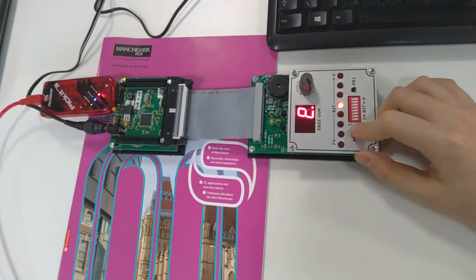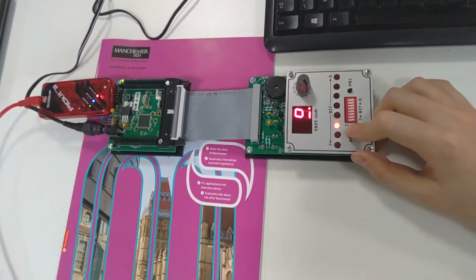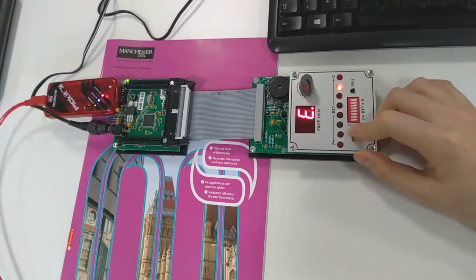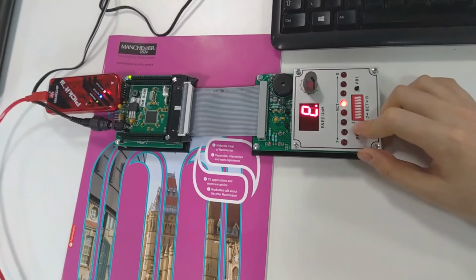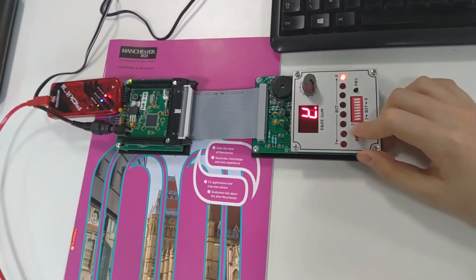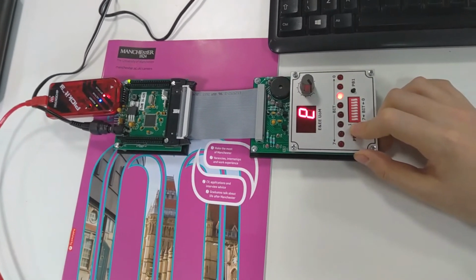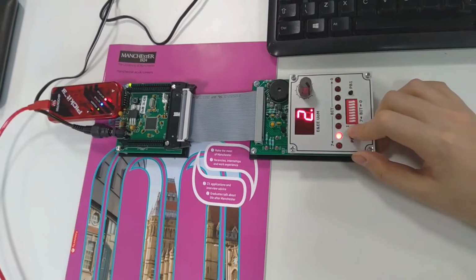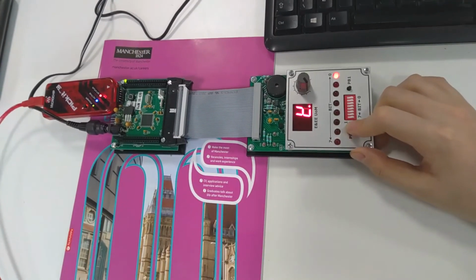So this means the functions of both push buttons, all 8 red individual LEDs, the piezo sounder, the 7-segment display U1 are all functioning alright, except that very piece of 7-segment LED component on U2 that is not functioning when it should be.